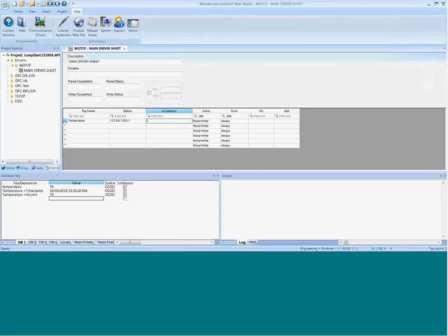Most Modbus PLCs start, for a holding register, at memory location 40,001 or 400,001 or 4,001. They're all the same in the way that I just said that. It's memory type 4 and then offset 1. So what we do is we're going to put in a 4x:1 because that's memory type 4 offset 1. So that'll be the first holding register. Now that should communicate just on its own there.